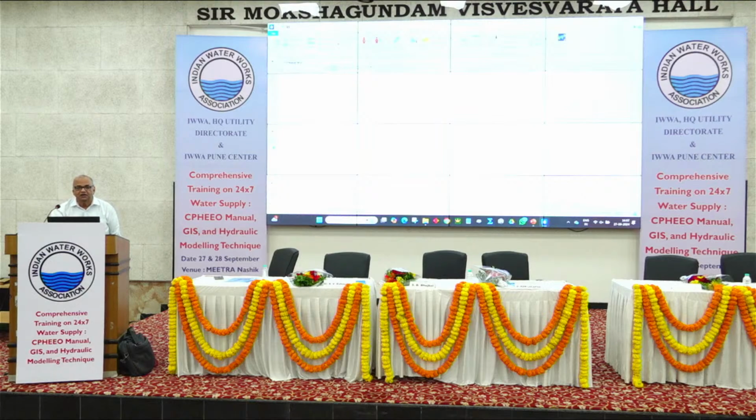So you have to go here, tools, then in tools, drawing. Now here is the unit. Here, the SI unit should be given. Wrongly, in that case, US Customary, this FPS system was given, and the whole model was in vain. SI unit means meter, kilometer, etc. So now the unit has been given correctly.